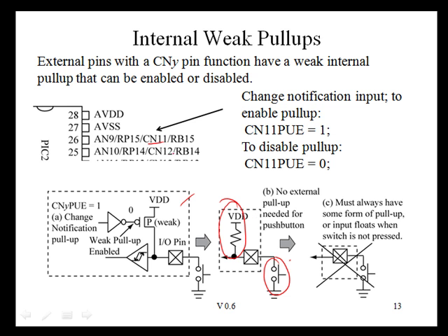Each parallel port pin has a corresponding special function register bit that will either enable or disable the pull-up resistor. Whenever we're using a push button input on a parallel input pin, we will always enable that internal pull-up resistor. You never want to use a push button switch without some form of pull-up resistor, either internal or external. It turns out that the pull-up resistor is actually implemented by a PMOS transistor inside the port.